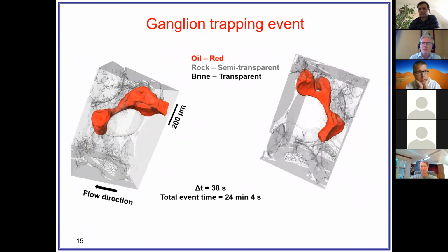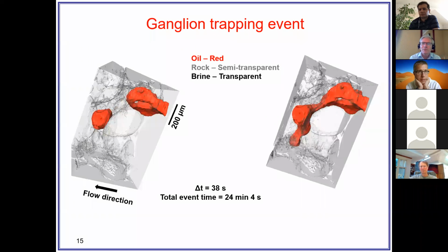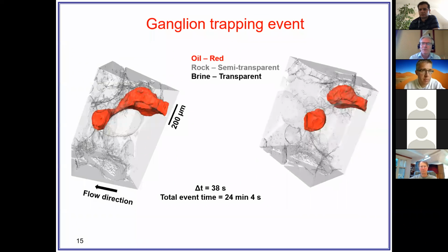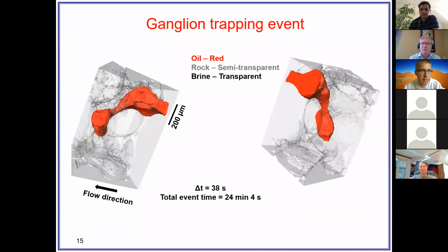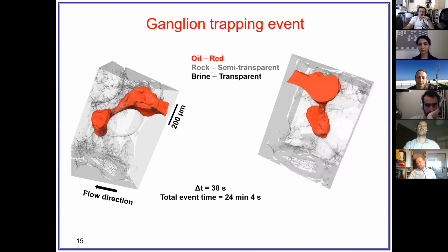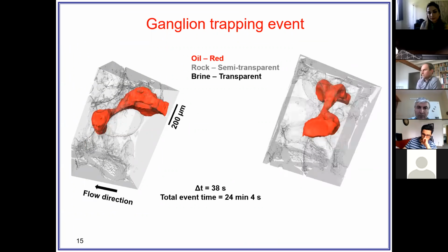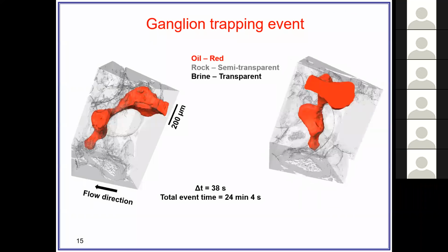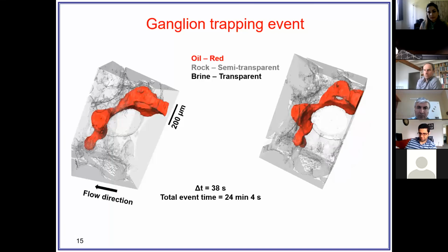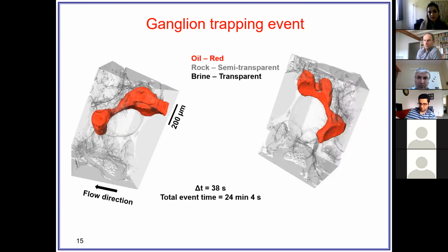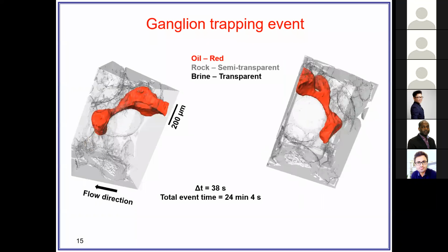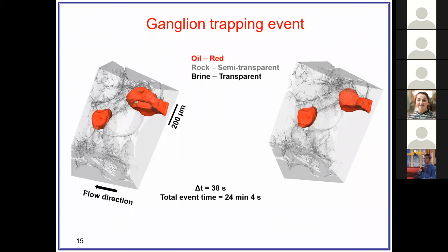The next question is from Isa Mohammed, who would like to know if the precipitation or deposition of asphaltenes impacts your measurements, and how such phenomena impact the quantification of wettability. Okay, very good question. In the experiments I've shown so far, we've aged in a crude oil, and we've either done the experiment continuing with crude oil, or replaced it with a refined oil. In all of these